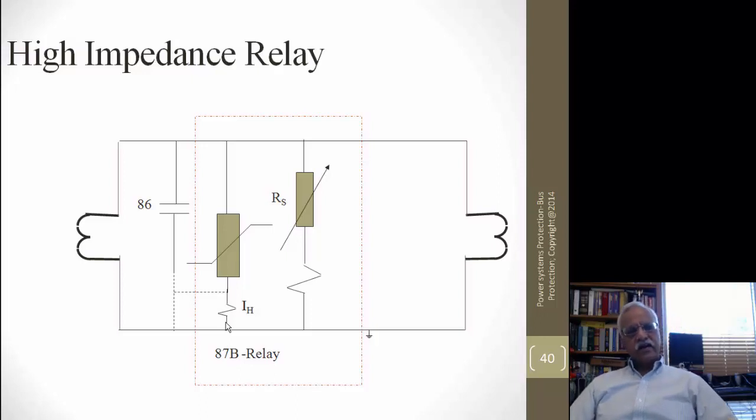As you see here, the basic requirement is that the CTs used for high impedance protection must be capable of developing the voltages required for the operation of the relay. And second, most of the CT ratios are generally the same, so that you can connect them in parallel, so the differential current will be equal to 0. If you have different CT ratios and connect them in parallel, you might have issues. But if you have CTs with different CT ratios available, then you have to use the same CT ratio to make them for a parallel connection, and then connect the relay to the full winding of the CT. This is explained in several application notes of the relay manufacturers.